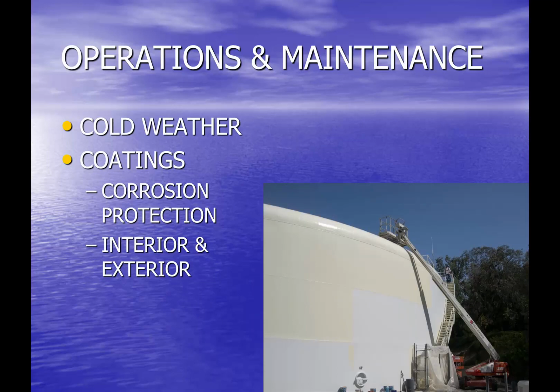Typically the interior is going to be a bit harsher environment. You'll see estimates of the useful life of coatings. I've seen them in the 5 to 7 year range. In reality, we get much longer life of these coating systems than that. I am not, by any stretch of the imagination, budgeting to replace coatings in our reservoirs every 5 to 7 years. We're typically seeing 10 to 15 years, if not longer. And it's good because it can be very expensive.